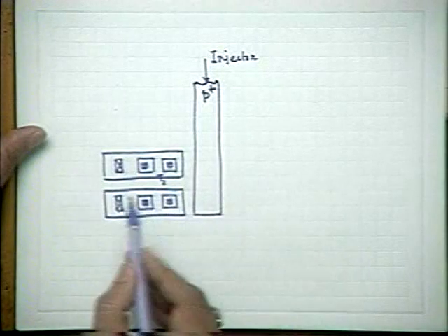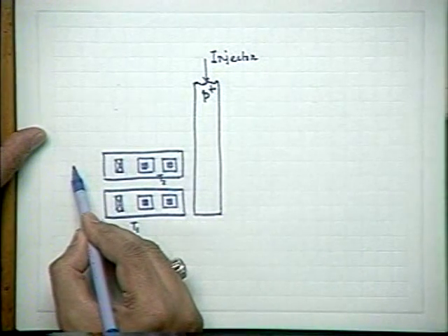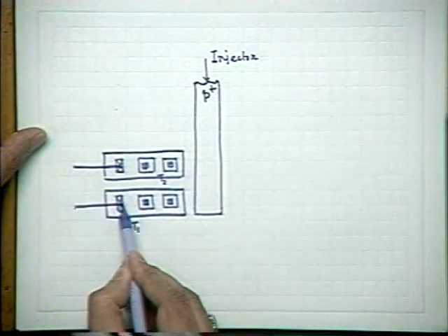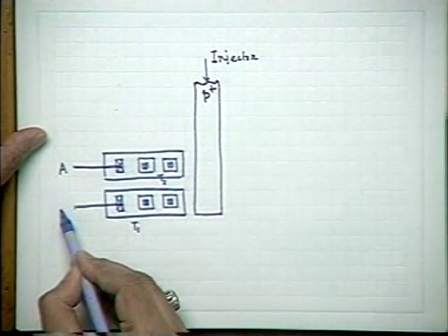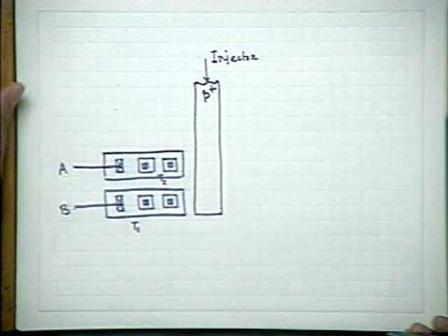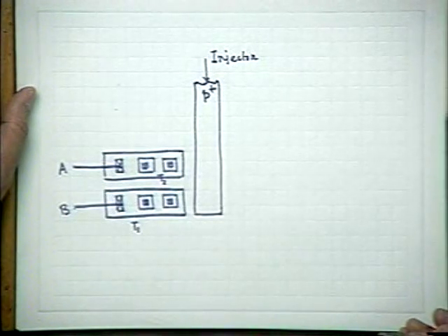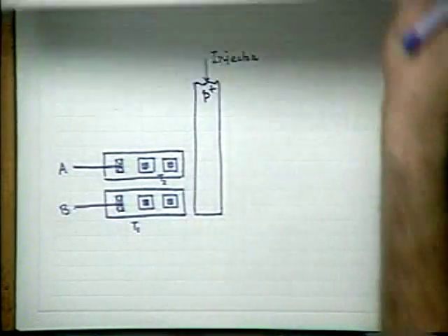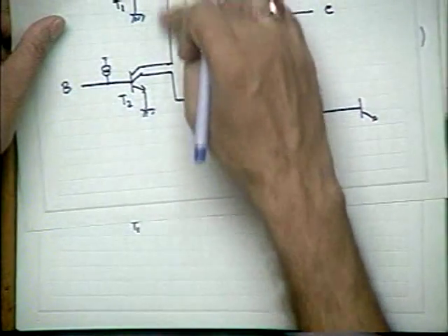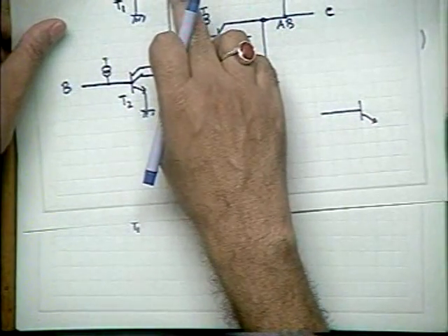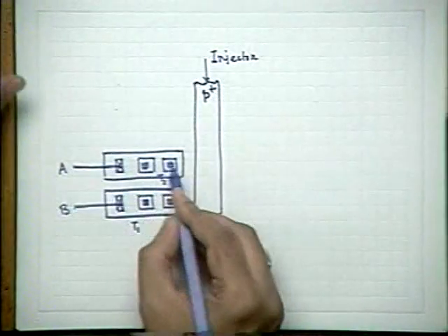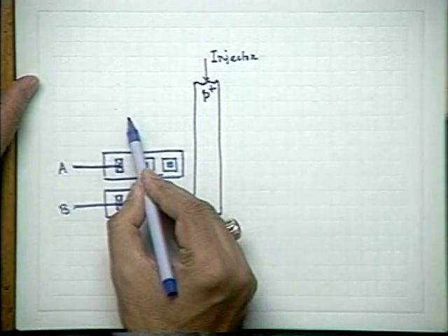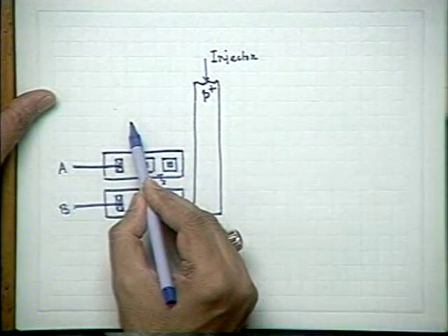Okay? And at the input, you are connecting your A and B, please remember. Now, one of these collectors is connected to form that A plus B, or NOR. So I'll just connect them and transfer to the base. So I'll put the third transistor T3 here.